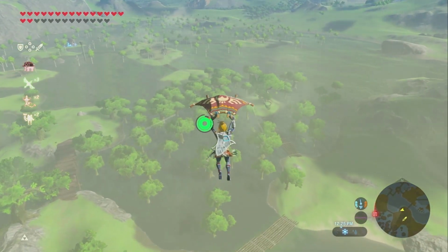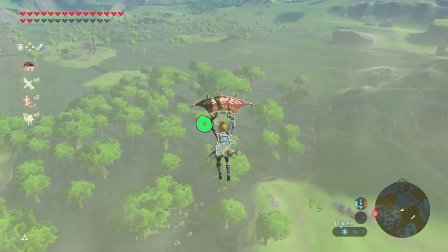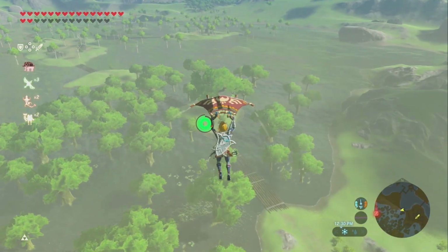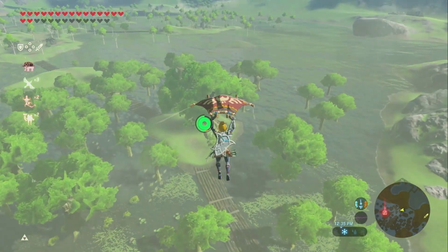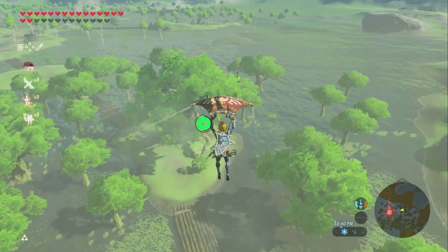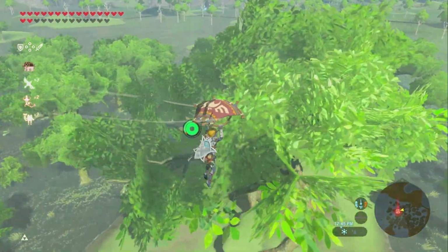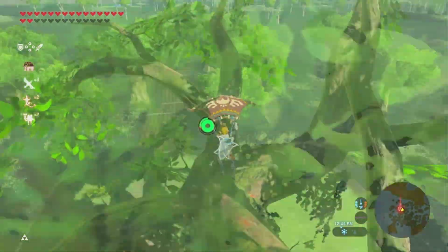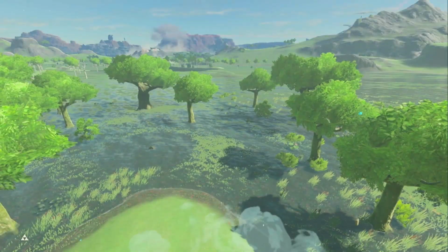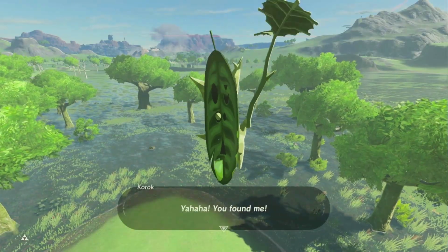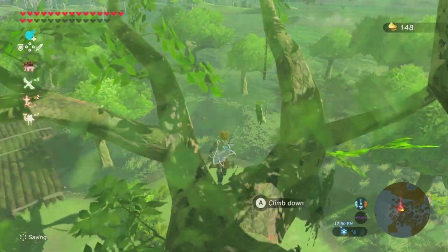1. Missing relief valve. 2. Undersized relief valve. BTU rating less than water heater. 3. Missing temperature protection. Pressure relief valve only, no ECO. 4. Poor location for temperature sensor of temperature/pressure relief valve. Must be in top 6 inches of tank. 5. Shutoff valve between the pressure relief valve and the tank are installed in the discharge tube. Not allowed.